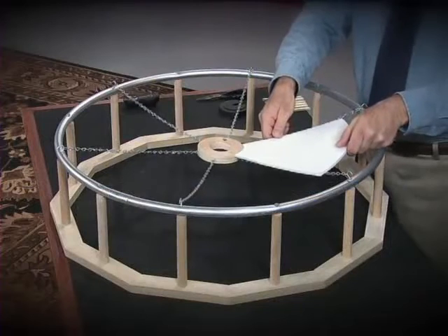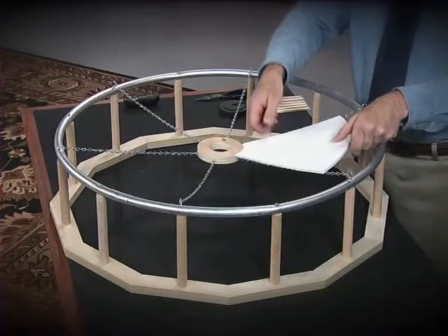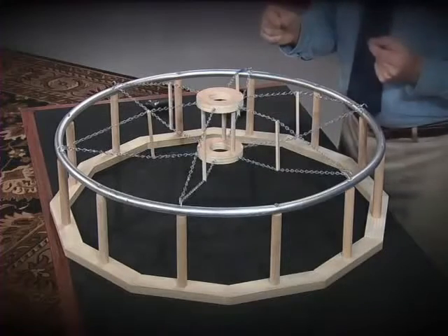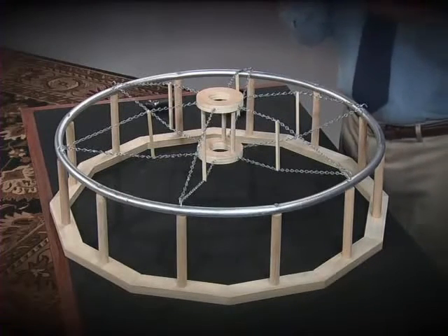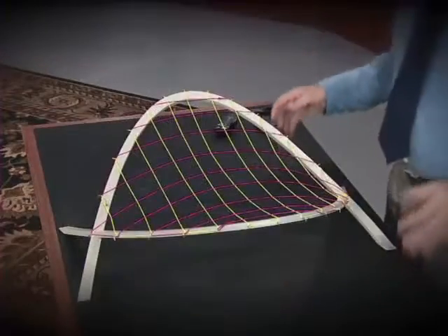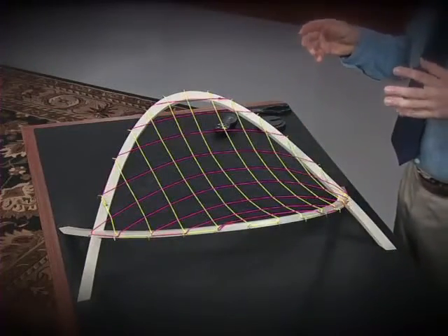It's at the interfaces between cables and the compression ring of Madison Square Garden's hanging dish, between cables and the vertical struts of the Utica bicycle wheel roof, between cables and the concrete arches of the Dorton Arena. It's at these connections where we can see the principle of equilibrium playing out so vividly. And because the cables differ so visibly from the compression elements in these structures, we can clearly see how their internal forces counterbalance each other, how they interact to make the structural system work. And there's a special joy to seeing and understanding structure in these systems.